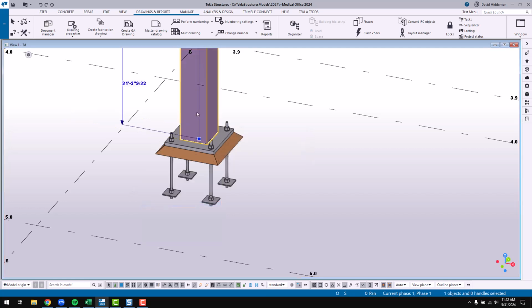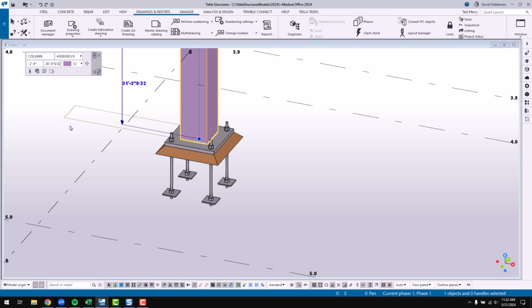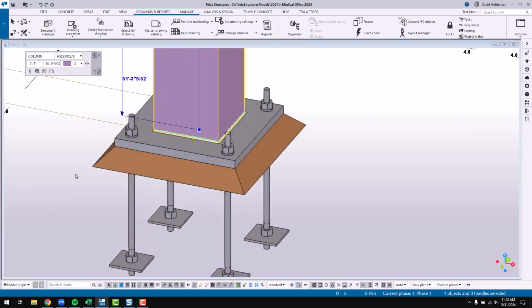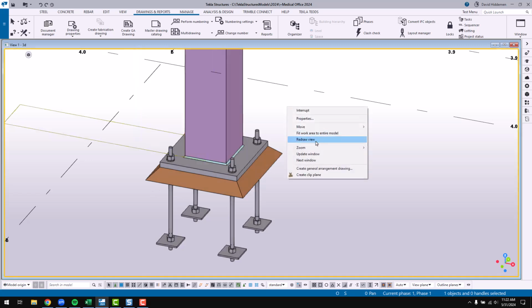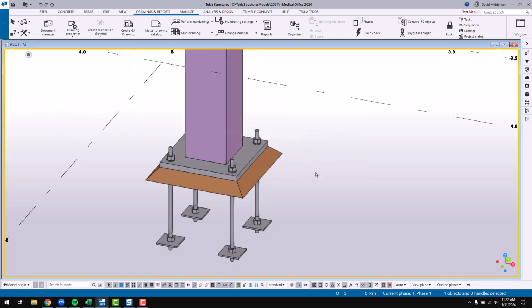The idea with that show detailing is that I can click that button and see the welds and cuts associated with that part. So any sort of what we consider detailing is cuts and welds and bolts and holes and things like that. It gives me a quick display of those. And as soon as I redraw the view, they go away to whatever the current view settings are.